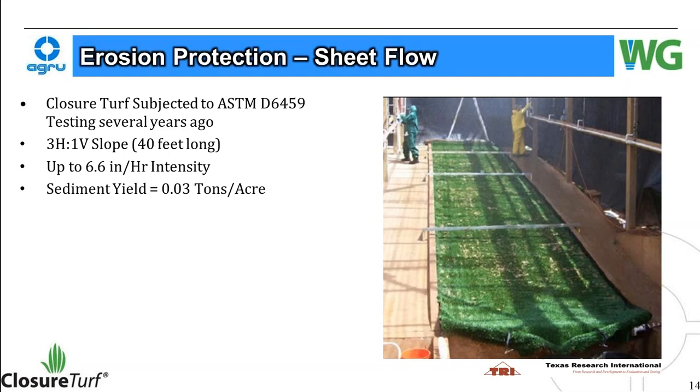The sediment yield was well below the nominal 2 tons per acre. It does have a curve number of 94 or a corresponding rational method runoff coefficient of 0.76. So pretty much all the water that hits this system is going to flow off of it. We'll get to how to deal with that in a bit.